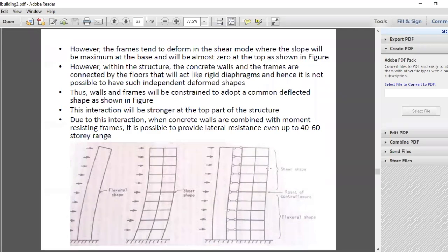Yes. So actually the situation is, when you consider wall frame interaction, it can actually reduce the deflection, but still the wall is a fairly strong element. Although its deflection is high, it cannot deform in an uncontrollable manner. So because of that reason, throughout the height of the building, we can consider the frame is braced.